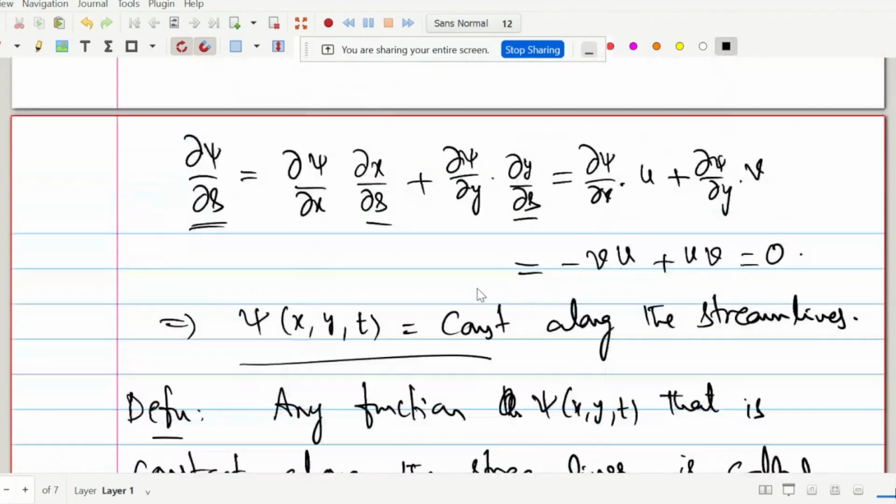No, sir. Fine, right? So why do we say stream function? Because along the streamline, this function is always constant. That's what we have shown. Dou psi by dou s, where s is the parameter along that streamline. If you take the total derivative along that curve, dou psi by dou s is nothing but grad psi dot product with the tangent.